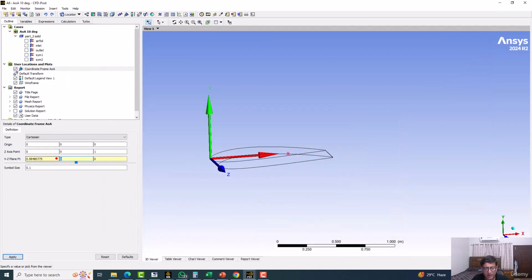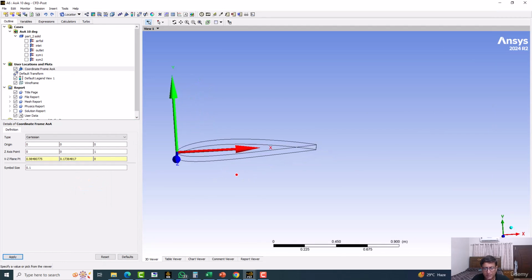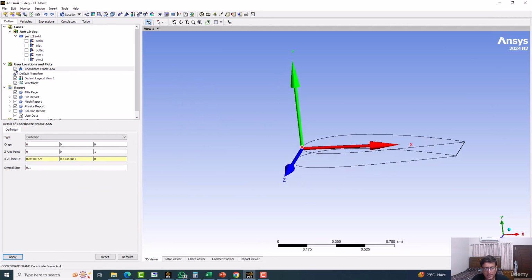So this will rotate only the xy axes, not the z-axis. The z-axis is put at the origin 0 0, and the second point is put at z equal to 1. Actually 1 or 10 doesn't matter, you can put 10, it will not make any difference. The vector direction is important, not the magnitude.